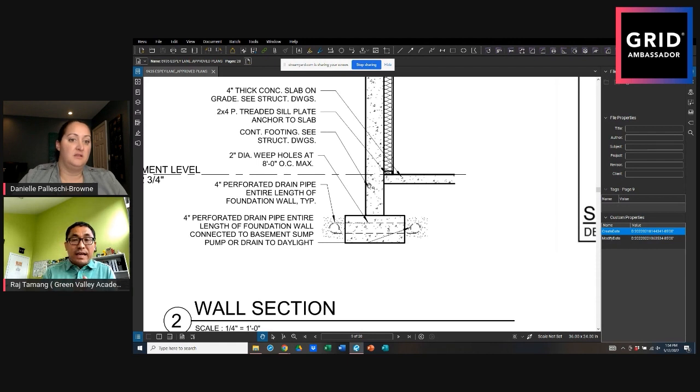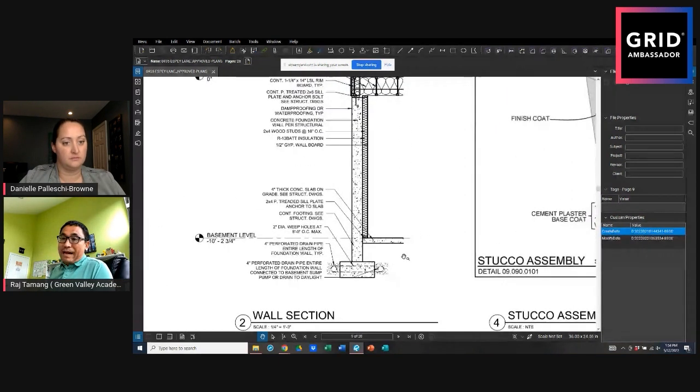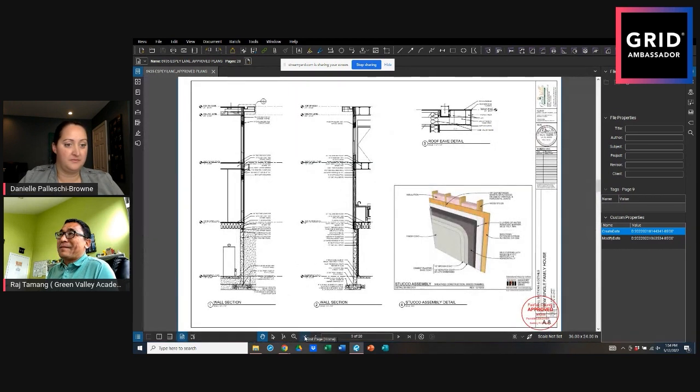So I always tell my project manager, before you pour the concrete slab in the basement, make sure you go there and it is clear everywhere. You have to put a rod in and make sure it's completely clear and everything is properly connected where it's supposed to be. Then pour the slab, because after you pour the slab, it's too late. You can't go back and put the weep holes in, unless you tear up the whole thing.